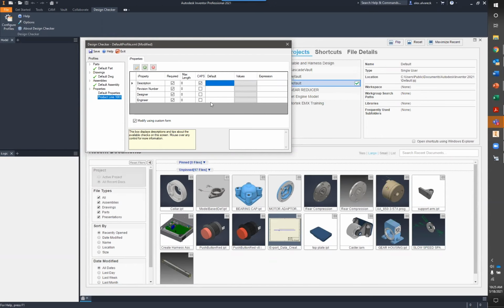So again, it's telling us that the machining folder has a few issues, and then the modeling folder has a few issues as well. So what we do is we take a look at these folders, right? It tells you what's passed, and it's telling you here what's failing at the moment. If we take a look at the machining folder, it's telling us that there's an invalid hole increment, right? Well, that's interesting. If I take a look at this invalid hole increment, I can actually right click on this error, say edit, and it'll bring up the actual command for us, right? So especially if you have a pretty complicated part, you don't have to go in here and search for that feature.